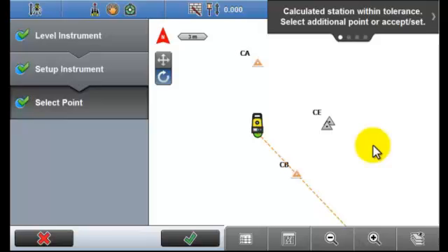I mentioned before that a minimum of 2 targets are required for a resection. However, it is always recommended to use at least 3. This will greatly improve the reliability of the resected residuals and guarantee that no mistakes have been made. It is also recommended to always include at least one prism measurement when setting up a total station. This measurement should be accurate for height, and it serves as a check on the manually aimed observations.